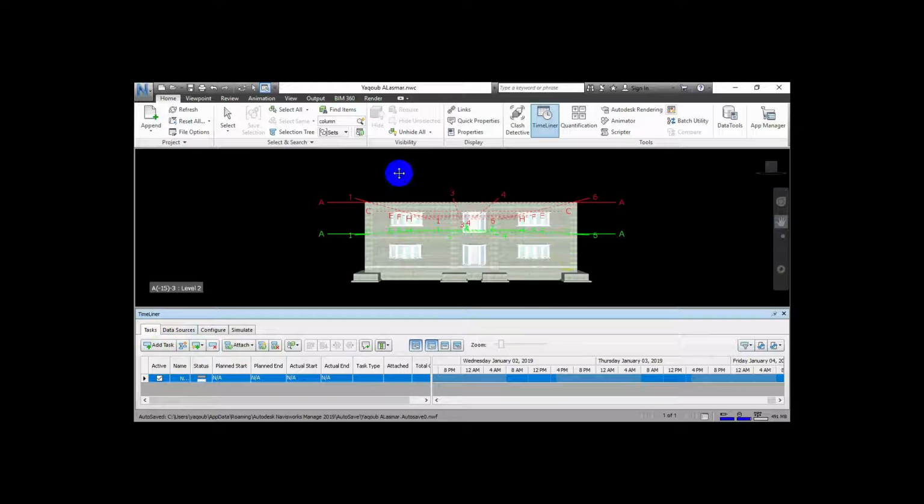For example, in our project we did our timeline by Primavera, and now we want to assign these activities in Navisworks. Let's say we will start in the beginning with the clear cover under the foundation. Name the activity clear cover.